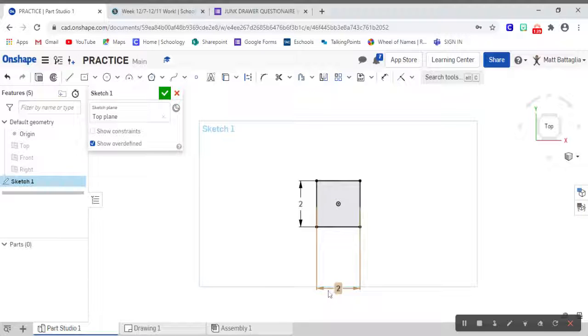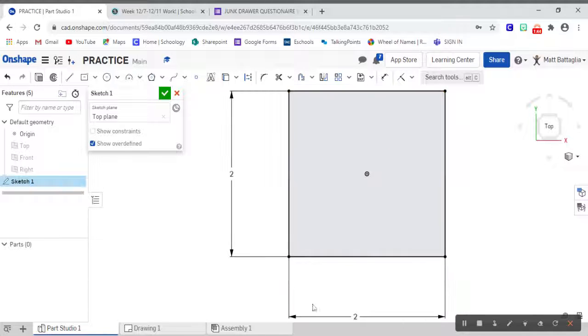And I'm going to go ahead and do a quick right click, zoom to fit, so that you guys can see this a little bit neater now. Now, there is one other thing that I would like to do before I finish my sketch, and that's go ahead and create a 1" diameter circle, again, using this origin as my center point. So I can go up to center point circle, left click it to highlight the tool, make sure that I'm getting this orange box constraint, click, click, and then type in 1, enter.